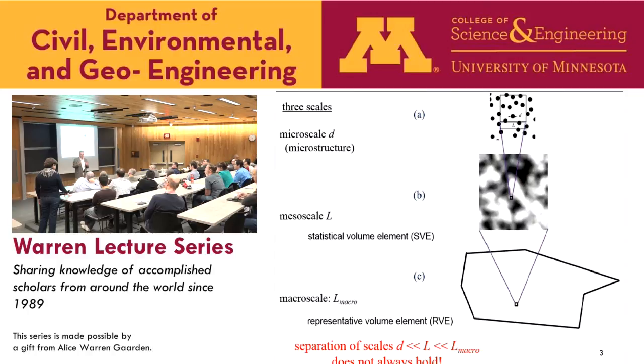And now, if the wavefront is comparable to grain size, then the moduli which come into the governing equations are random fields. So then the competition is stochastic for blow-up of the wave. Whereas if the wavefront is smeared over 100 grains, and the Hill condition will give me an indication, am I on the RVE level? How strong is the noise? Then noise is irrelevant. So this should be used as guidance.